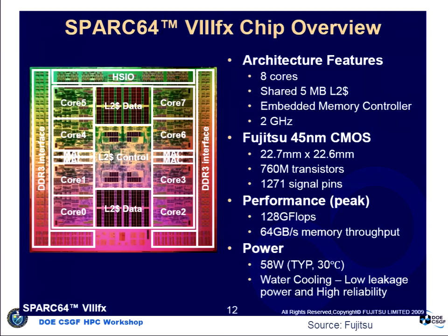It's also got a very large number of processors and also a correspondingly large amount of memory in it. If you look at the chip itself, it's an 8-core modified SPARC64. Everyone thought SPARC was dead, but the Japanese took this particular chip, added vector units to it, and made it a very impressive supercomputer chip. It's 128 gigaflops in about 58 watts of power in that 8-core chip. That is the heart of the K system.